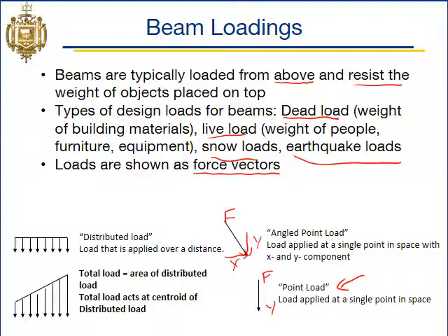And then getting into our more complicated loads, we have what's called distributed loads. This is a load that's applied over a distance. Good examples of distributed loads might be flooring material. You put flooring material over the entire area that you're building, and we would model that each tile has a certain weight and a certain size.